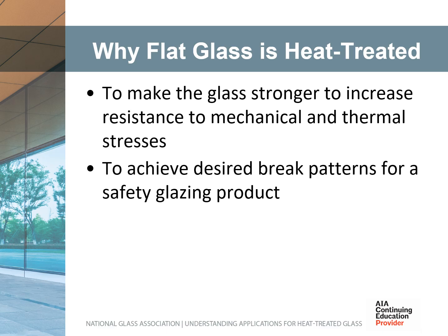Tempered glass not only provides a significant increase in glass strength, but is also a safety glazing material when it meets a safety glass standard. Because tempered glass breaks into small particles, it significantly reduces the risk for injury from impact. If there are concerns from glass fallout, laminated glass or a tempered laminate may be used.